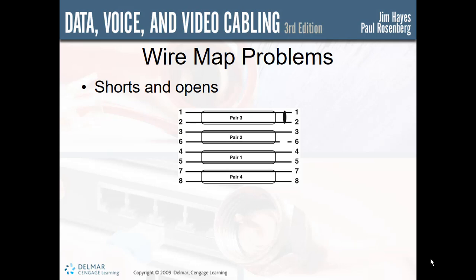So a TDR, which is called a time domain reflector, sends a signal down the wire, which then bounces back and gives you the distance. So if we're sitting here and we have 7 wires that are showing 75 feet in distance, and 1 wire that shows 35 feet in distance, we know that that 1 wire has a break in the line.